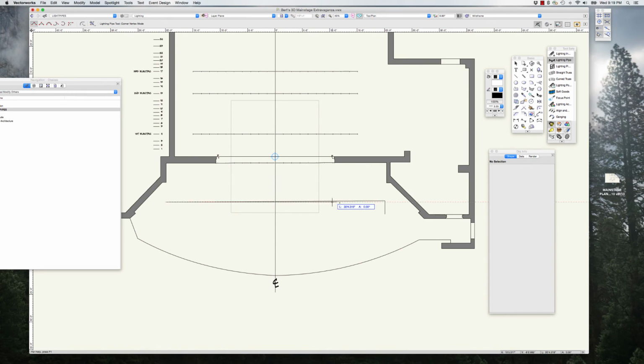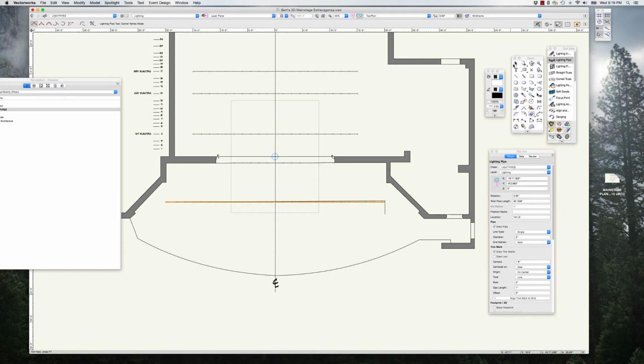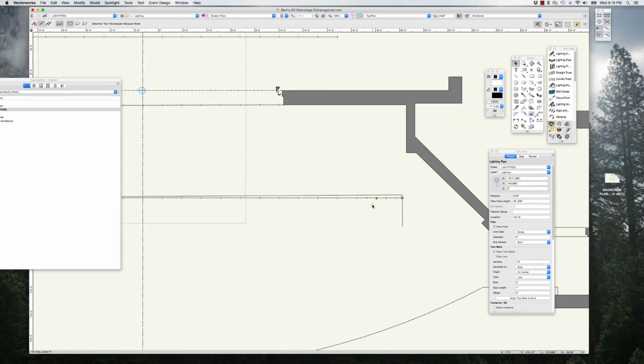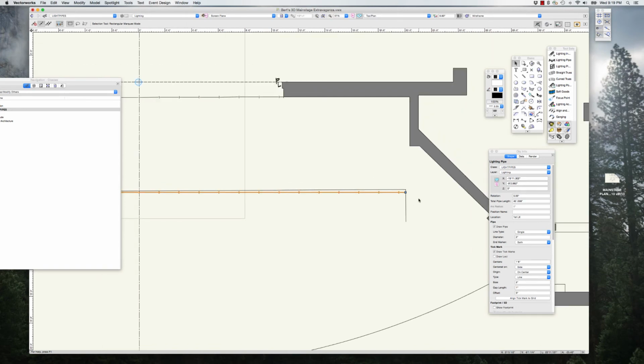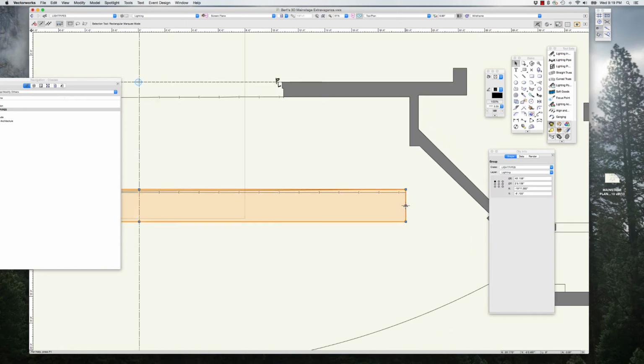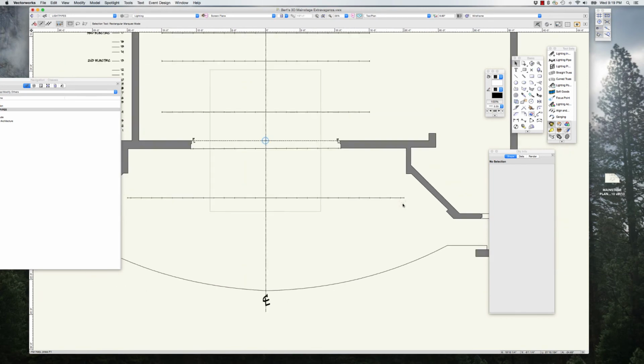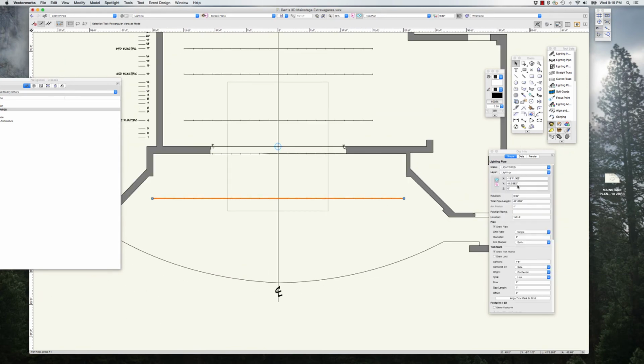So I'm going to hold down shift, and it's not, while I'm drawing this line. I'm going to make that one straight. But if I had originally drawn this line straight, I wouldn't have been able to select it because it would have been under the other line. So that's why I put the handle there, so now I can delete that. And we're going to say that this is probably 15 feet. Maybe we're going to have to take a look at this one.